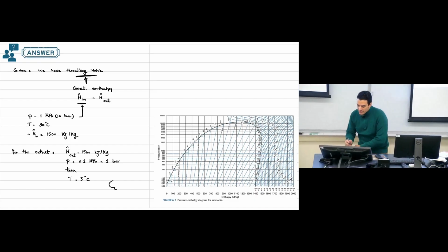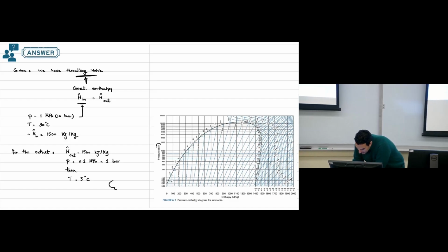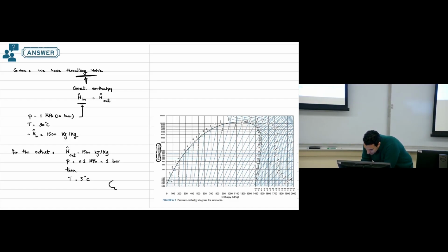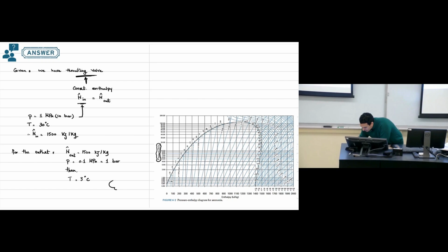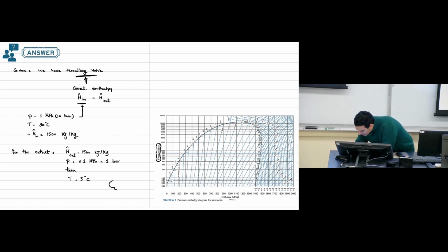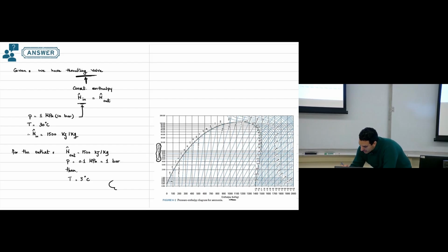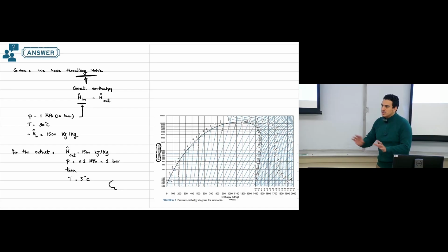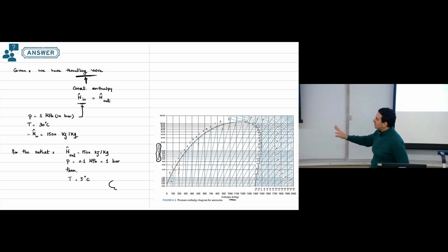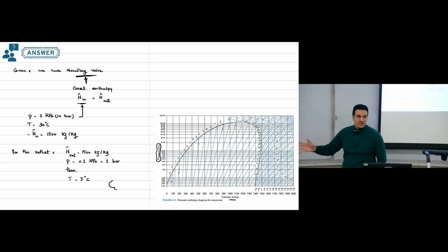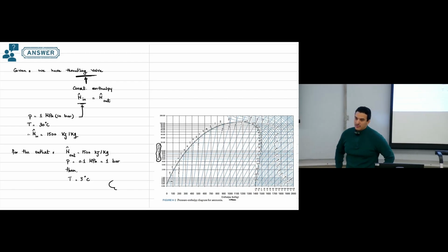So basically we have this figure. For any value of pressure given, just put it on the y-axis. Let's say we have the enthalpy for the outlet. We can see the intersection between these 2 points, and then we can figure out what the temperature is. So this is the easy thing. We have figure, we have tables, use the figure, use the data available in the table,